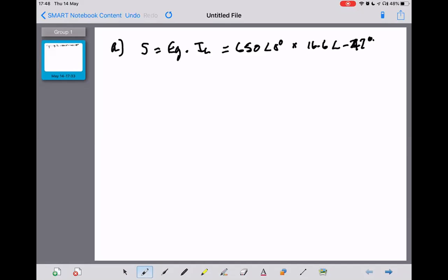It is simply the magnitude of the voltage times, because remember, you've got 3 different powers you can deal with: S, Q, and P. So if the line current is the actual current flowing in the line, that's the current that gives you S. There is an angle, but at this stage in the calculation, you don't need that.